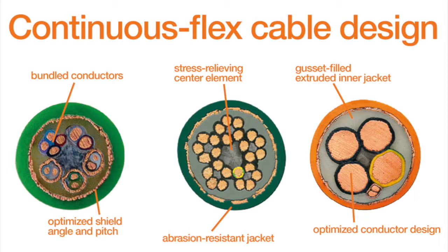If we have a plastic cable carrier, there's a better chance that the abrasion resistance doesn't matter as much, because the plastic won't be as harsh on the outer jacket of the cable. But if it's installed into a steel cable carrier, we could have some more issues, and they could happen much more quickly if you don't have an abrasion resistant jacket. So the more we can protect it up front and have the right material for that outer jacket, we can move forward from there.